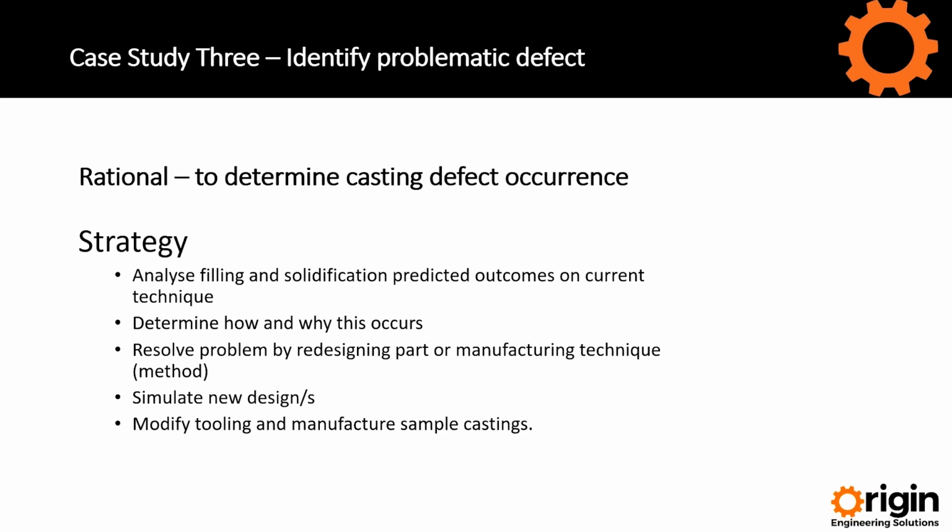Now, like I said at the beginning, you can do the casting simulation, and if it's tuned in correctly, you know the technique's right. Because like I say, the operators can influence a good and a bad casting if you haven't done everything correct and put the right data in. You've got to have the right pouring temperature, the right die temperature, and make sure, for us as gravity die casting, we use the right die coatings, have the right viscosity of the die coatings, applied in the correct technique.